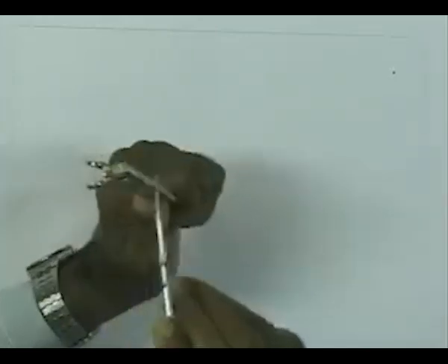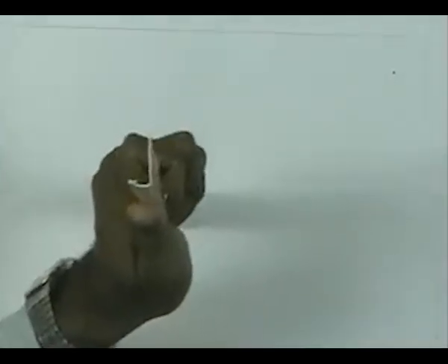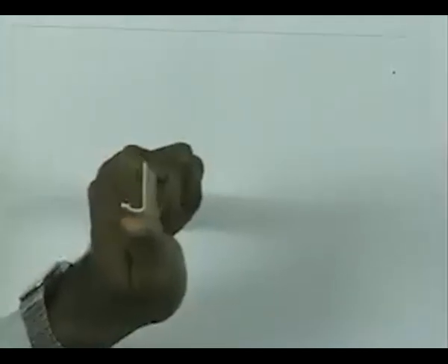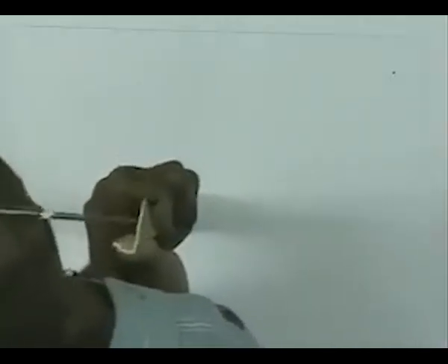So, it lies outside the cross section, you see, it is somewhere here, it is at a distance. This is for this section which has one axis of symmetry. Let us look into another example. Look at this example. Here this is like an L section. Now we do not have any axis of symmetry here. If I put the loading parallel to this edge, let us say I put this load there, you see these sections rotate, and if I shift the point, see here the rotation has reduced. Therefore, if you come to this corner, it does not rotate.